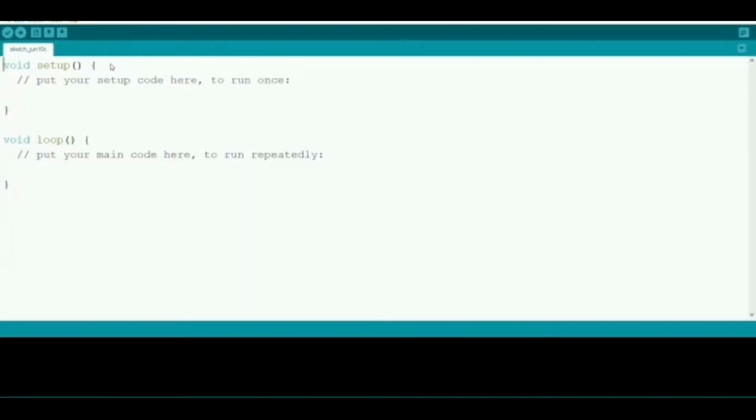Welcome to the segment where we will see the zero setting of the servo motors. First, we will start our program by adding the servo header file, which helps us to use predefined servo functions and also helps the Arduino board to control servo motors. Then we will declare variables servo1, servo2 and servo3 for each servo.